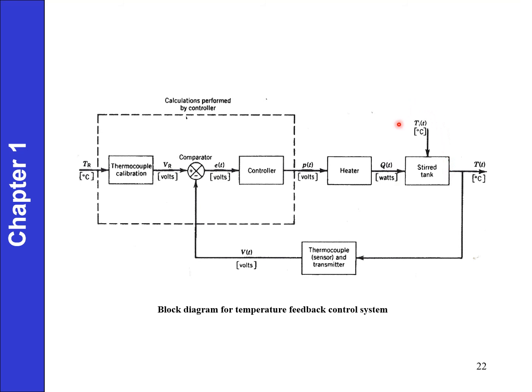Okay, and this is the valve that we are going to use in the stirred tank, and this is the output from the stirred tank, and it will go through this closed loop, and then it goes back to the set point, to see whether it is in line with the set point or whether it increases or decreases. Okay, so the two things that you must remember are how to draw the schematic diagram, and the block diagram, in this case for the temperature feedback control system.